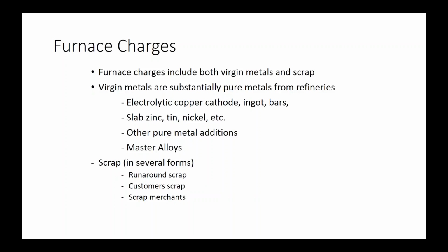And then you get scrap from scrap merchants. This has to be vetted and carefully taken into account who you're buying it from and what you're buying, and that you don't get something you don't want in there. The use of scrap lessens the use of virgin materials, but does not decrease the need for you, once the alloy is melted down, to check it out and make sure that you have the correct compositional parameters in place before you start pouring metal.